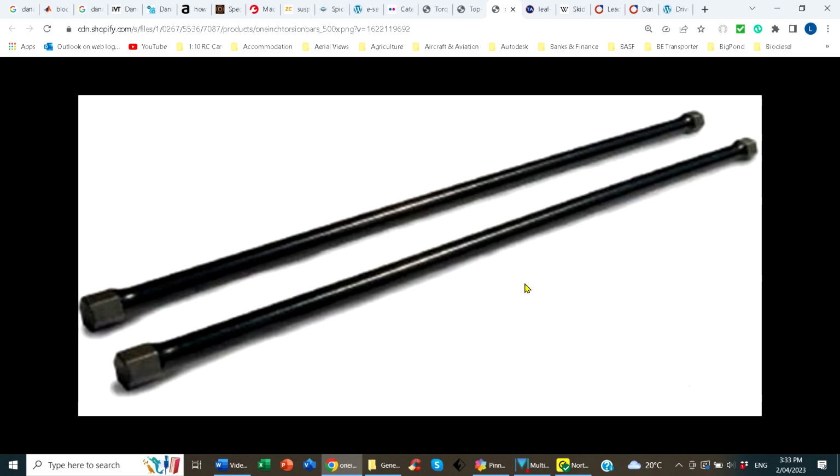One that you don't see on cars very often, unless I think you've got an old VW. These are torsion bars. They're a long bar with splines on each end, and they're twisted. Usually there's an arm off one end that takes the vertical load from the wheels and imparts a torque onto the bar. And the bar resists that torque, hence torsion bars. They are really great for low floor heights in vehicles.